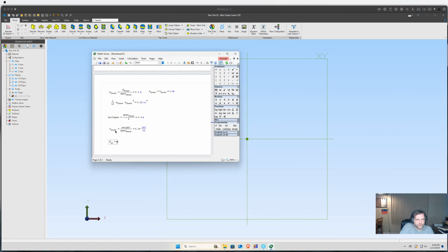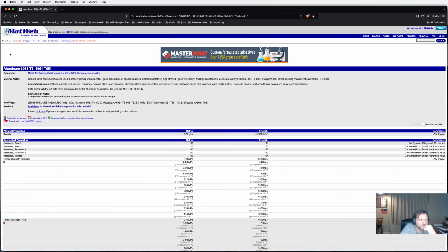And another aspect is another crazy approximation, because we're really simplifying things. We're going to say that this is aluminum. And why is that? Because aluminum is a relatively homogeneous material, meaning it doesn't change a lot. Sorry, I wasn't showing that, but aluminum doesn't change its material properties a lot like composite does. It's a lot simpler to analyze than composites, and this is our first approximation. We could always look at composites later.